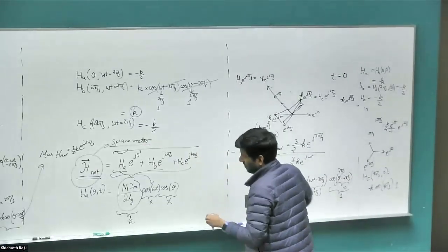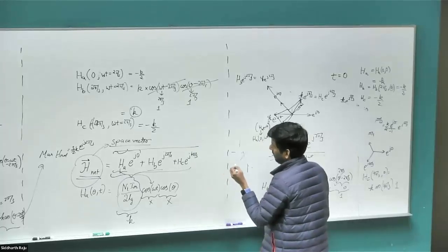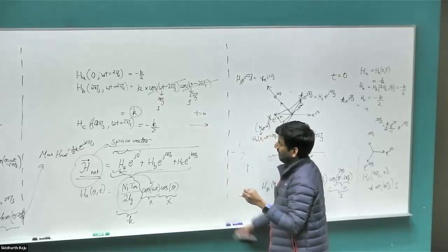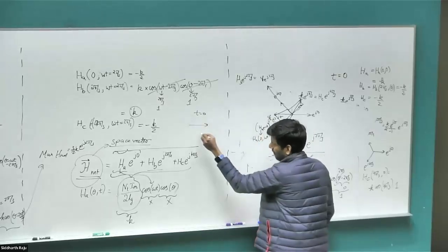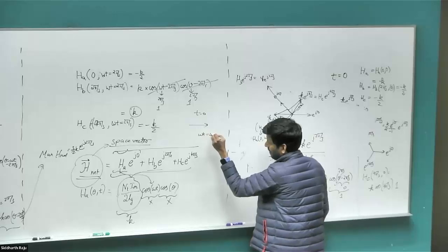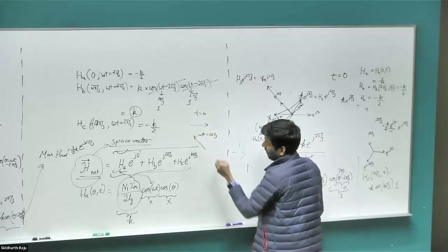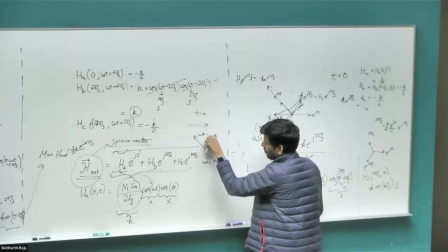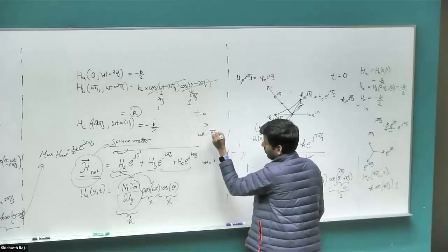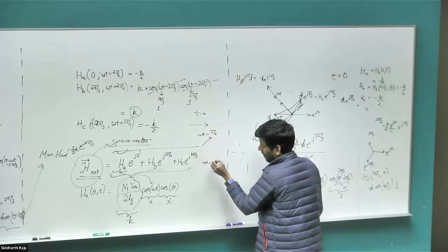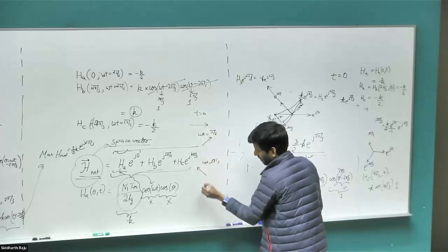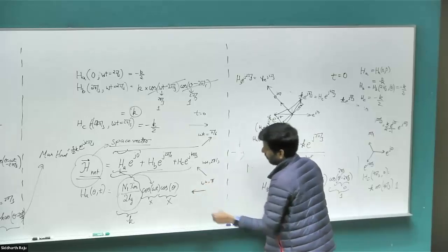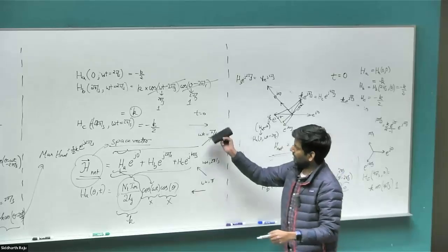It tracks where in space our magnetic field is at its peak at any given time. So at time t equal to 0, your H field will be at its peak at angle 0 degrees. At omega t equal to, let's say, pi by 6 first, it will be here. At omega t equal to 2 pi by 3, it will be along the b axis. At omega t being pi, it will be along this axis, and so on and so forth. So this is where the peak H field is.